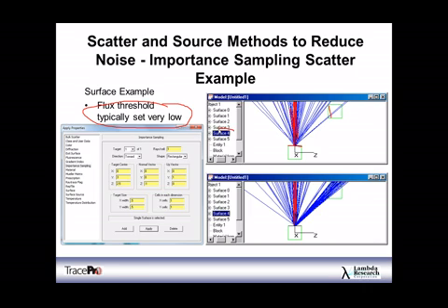So what I do is I grab that surface, the top surface, and I specify a target area towards my target. So I put it on this surface that's the top of the box, towards this area right here, which I specify with a target center, a normal vector, and a target size. Right now this is a rectangular area, and I hit apply, and now there's an importance sampling target on this surface to send light in that direction. And when I do that particular analysis, look, I get all these importance sampled rays. So that's how you do it, using importance sampling.